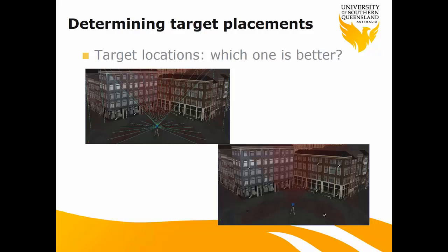In this one, we put targets at different height levels, different elevations, and we put at least one target not along this building surface. So certainly the second picture shows a good location for the targets, evenly distributed with different heights and even different ranges.